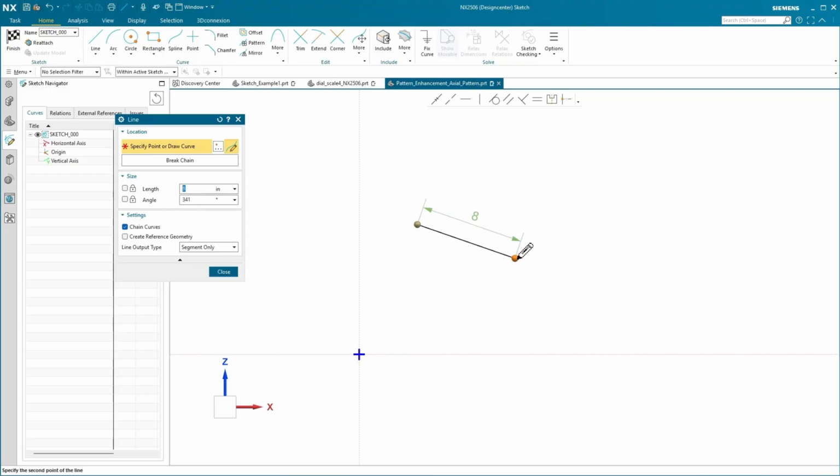If you want to go ahead and control the angle on that curve, you can easily go back over and type in a given angle if you need to, or you can go in here and you can lock the angle right there. So once you set the angle out here in the graphics display and position that, you can right click and you can choose to lock the angle here. And that way my angle has been locked.